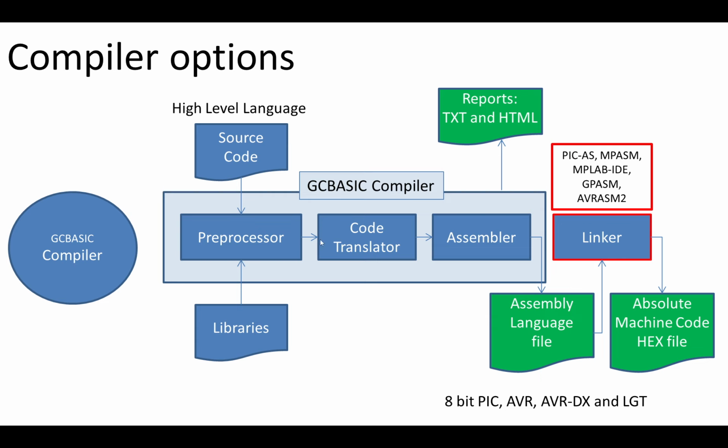And that is going to be like this. So we're going to come along, go out into PIC-AS, from PIC-AS get it to do the assembly and link it out, and then generate our absolute machine code. We'll get a lot more files as a result because we do get a lot more files with PIC-AS. Time-wise, not a lot of difference, but some people want to be able to do it. And this is the way to do it, to put it into the debugger.